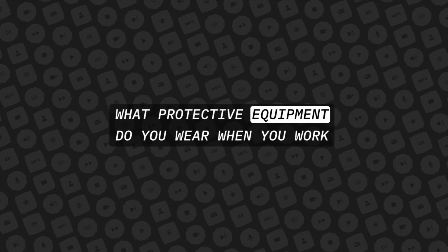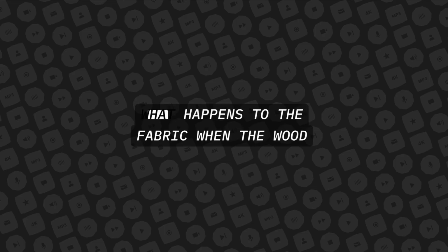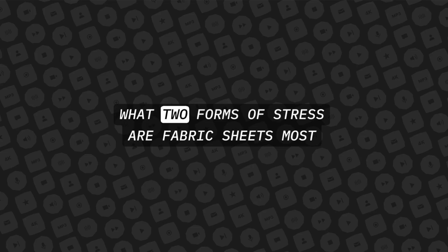What protective equipment do you wear when you work with carbon fiber or graphite? Gloves and eye protection. What happens to the fabric when the wood under it breaks? The fabric cracks. What two forms of stress are fabric sheets most susceptible to? Tension and compression.